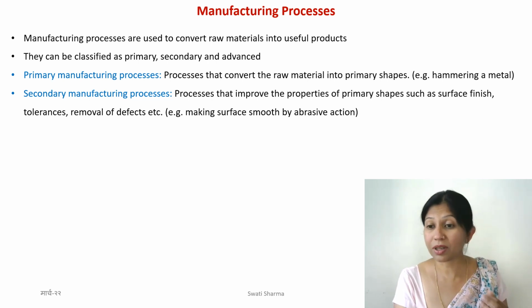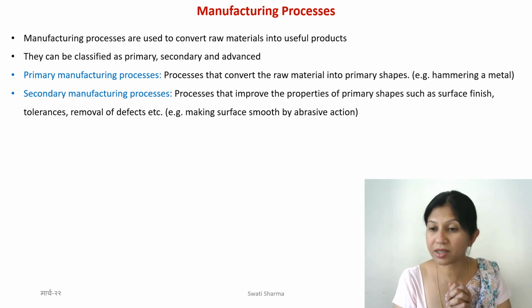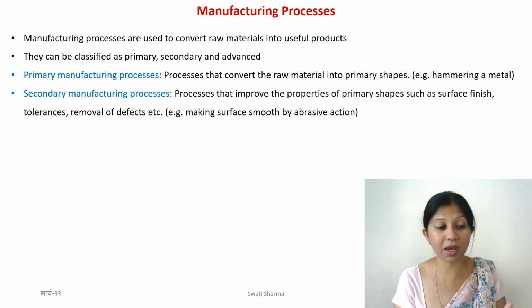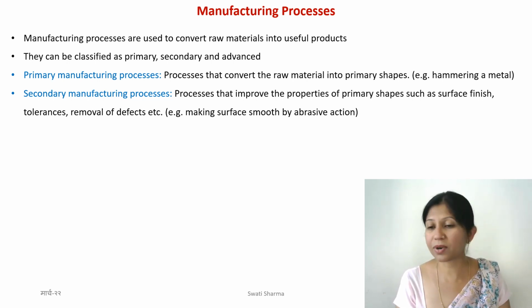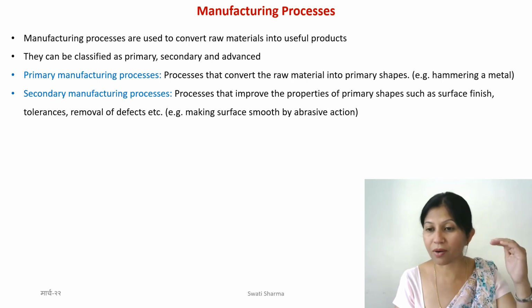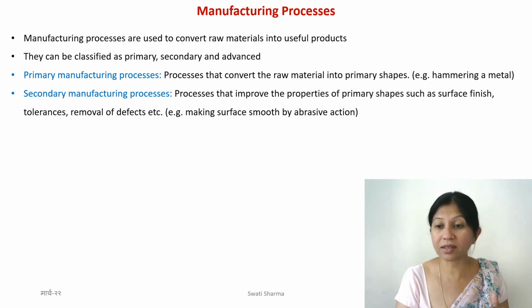Also, one more thing is that if you want to make something that is, let's say, 10 centimeters in size, but you get 12 centimeters, because when you are making it, maybe you don't have that much control. So what you need to do is also remove the material. Typically this will not happen, that a 10 centimeter part is 12 centimeters. Rather, it will be just a few millimeters up and down. And those margins are known as tolerances.